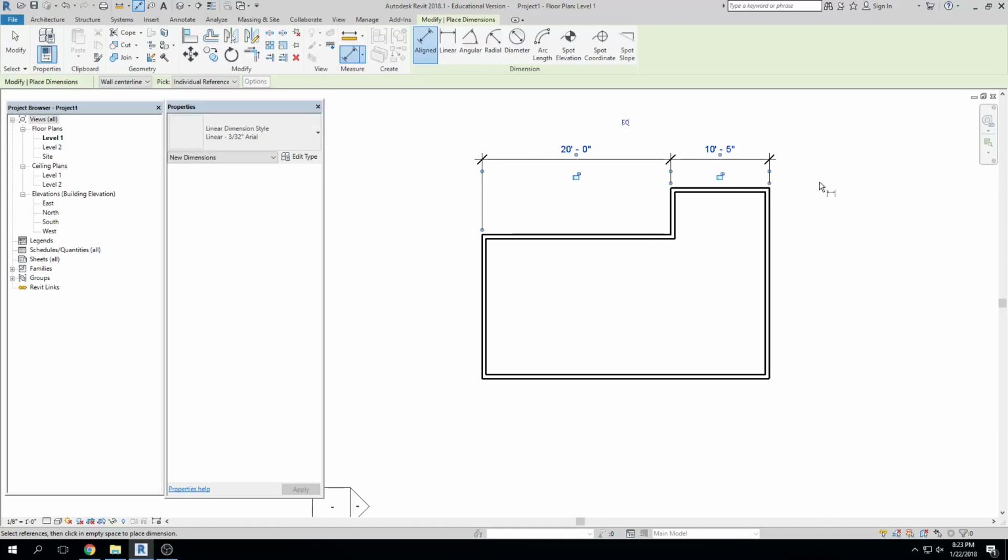I'm going to pull these dimensions because dimensions in Revit have a lot of integrity, and they will generally stay with the geometry that you assign them to, even if you move it or stretch it or do something with it. And that makes it really easy to visually see the modification that you're doing, right? So if I move that western wall back in 10 feet, I can see that the measurement above will go from 20 to 10 feet, right? And so you'll see me a lot of times keep dimensions on objects just so that I can track things that I'm moving.